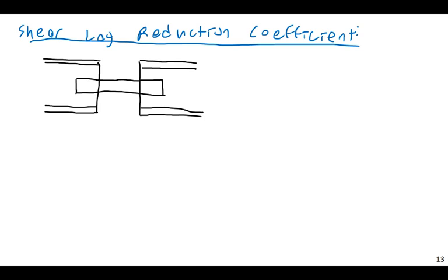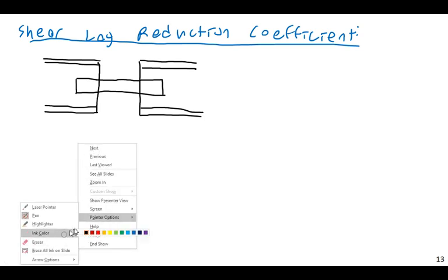So that's why in buildings, it's not uncommon to see stress cracks near windows. Wherever you have an interior right angle in a building, you always get stress cracks right near the interior corners of windows, because those are stress concentrations. The stress present in the material, in this case the drywall or the brick, has to flow around that opening, and so stress flows. And so let's think about how stress is going to flow through that connection.